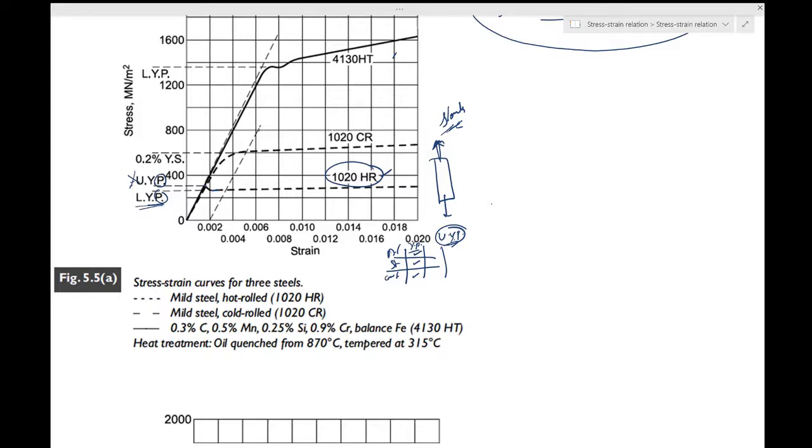As plastic deformation continues, the stress required for further plastic flow, termed the flow strength, increases. So the stress which is required to further cause this plastic flow is called the flow strength. Plastic flow is what plastic deformation is, so the word flow is used in plasticity. What it essentially means is plastic deformation. Similarly, you have something called a flow rule. This just tells you how the stress varies with strain, how the deformation happens, and so on.